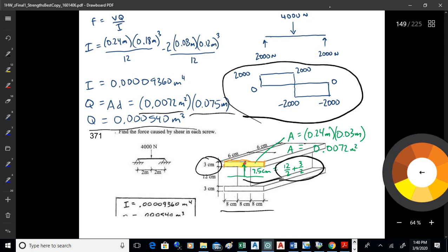So we're on this thing here, and we're looking at its tendency to shear off. See, when that beam gets loaded, everything's going to flex down a little bit, but that board's going to want to flex more than that big solid web underneath it, I think. They're going to have different radii of curvature. And when that happens, they're going to start doing that, or they want to.